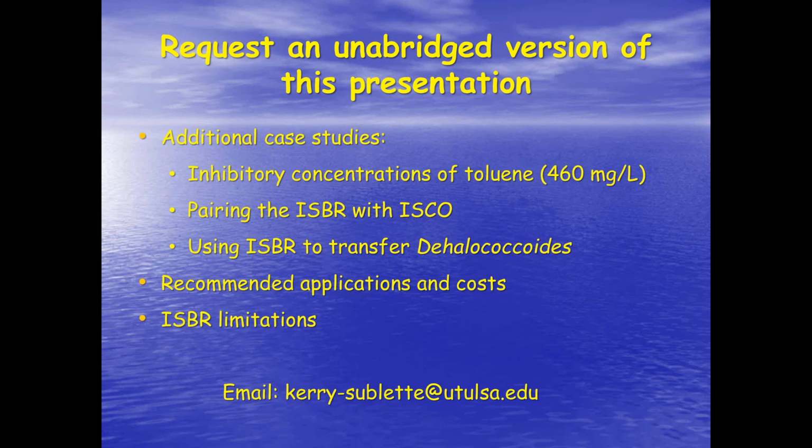The aquifer matrix here was a fairly silty type of material, yet we were able to show that we could significantly stimulate toluene biodegradation in a monitoring well located 10 meters away from the closest ISBR. It took about 3 months to do it, but we had significant increases in a number of different monitoring wells, but our star pupil was the one that was 10 meters away.